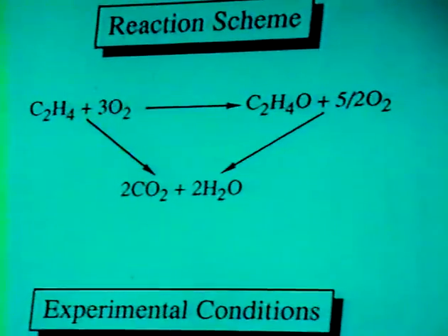So we did the experiment in an external recycle reactor, and we do a single pellet experiment. And if you see the next slide, here is a picture of the pellet itself. It's a single pellet, and it's about 2 centimeters in diameter. And the dark part here is the active catalyst. The light part here is the alpha alumina support. The active catalyst itself is about 33% silver loaded onto alpha alumina support.